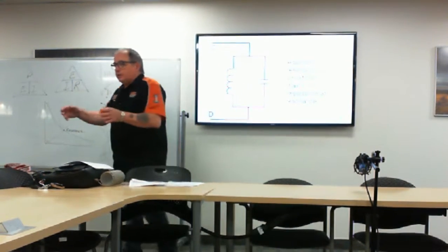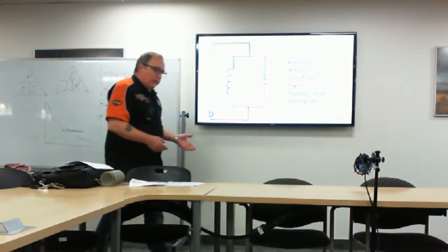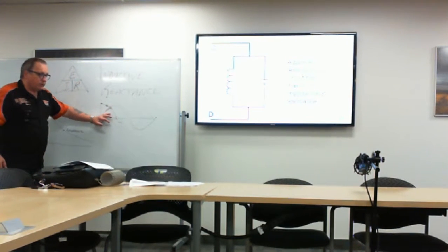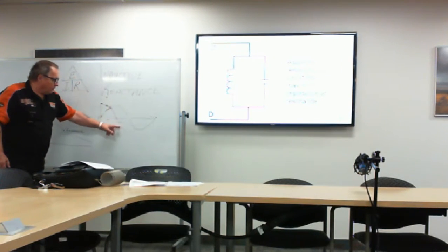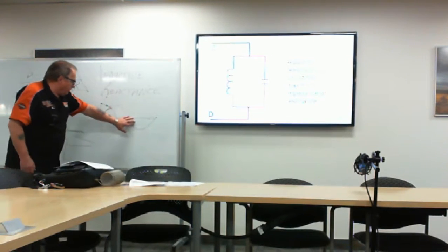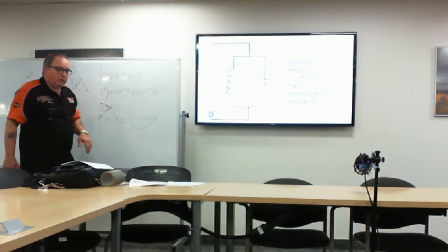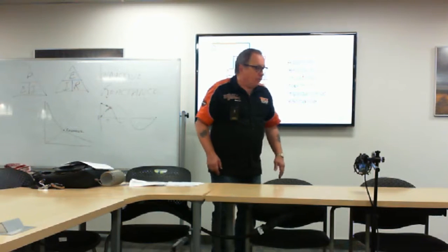So if all of your loads in your mill are AC motors, then you are paying for power you're not getting, because this is all the power you're actually able to use. Just under the curves is power. This is lost power. So what we do in industry is we take a capacitor.